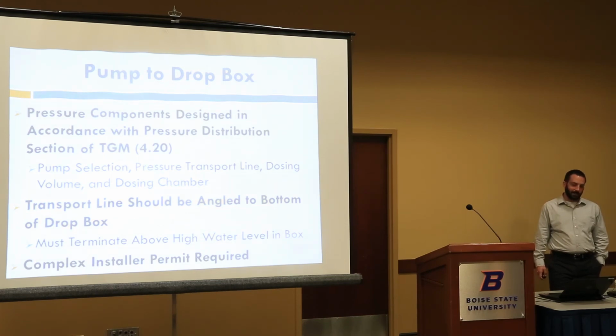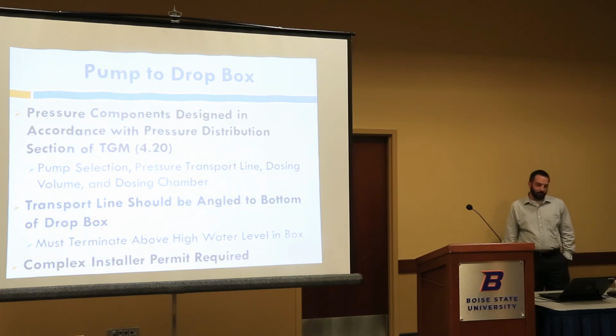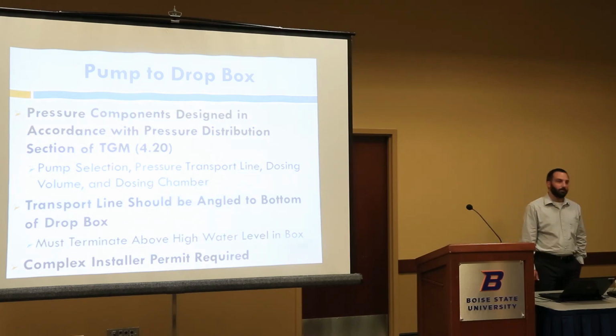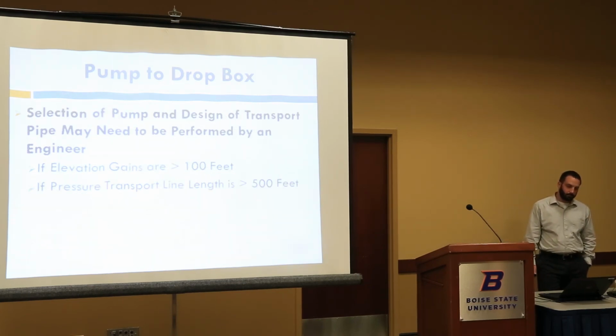Yeah, exactly. When you do enter the drop box with your transport line, it should be angled to the bottom of the box, and that transport line should terminate above the high water level in that drop box. And you do have to have a complex installer's permit to do a pump to drop box system.